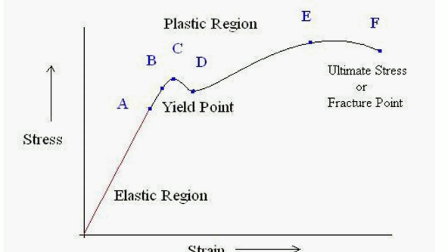Now again we are increasing further load. So whenever we are increasing further load, what is happening? It's coming to portion B to C. In this portion, the material shows a strain even without increase in stress, and strain is not fully returned when load is removed. So in B to C, two things are happening. The metal shows a strain even without increase in stress.